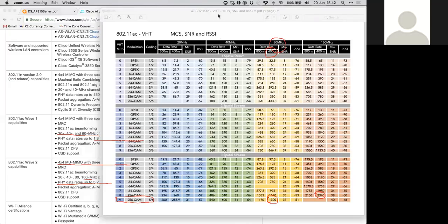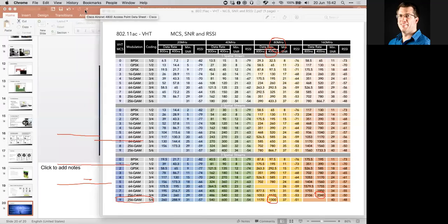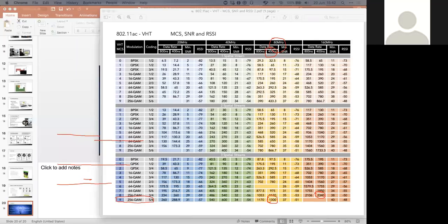Hey, Stephen, on that spec sheet, where are they getting the 5.2 gigabits? So let me just bring that up. It's defined in the standard, right? So let me just bring up another screen. I'll try and find it. There's a table on Wikipedia which refers to it. Let me just make sure I can find it. Is that on a single band or is that both bands combined? So I think they're talking about the dual 5 gig mode, and they're talking about doing 4 spatial streams, and they're talking about 5.2 gigabits per second on one radio, not one device. Let me just see. Okay, so they are talking about one radio, just not necessarily talking to a single device.